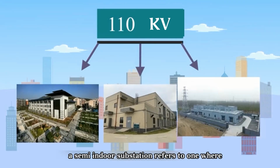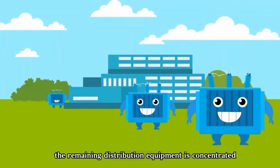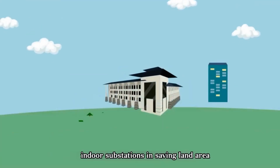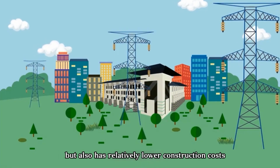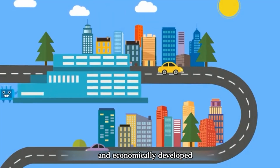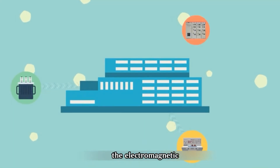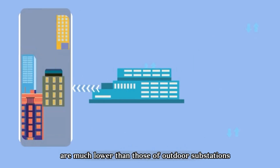A semi-indoor substation refers to one where, except for the main transformer, the remaining distribution equipment is concentrated in a production complex building. It not only combines the advantages of indoor substations in saving land area and harmonizing with the environment, but also has relatively lower construction costs. It is suitable for construction in economically developed small towns, due to the highly integrated layout, which places live equipment in one building. The electromagnetic and noise impact on the surrounding environment are much lower than those of outdoor substations.